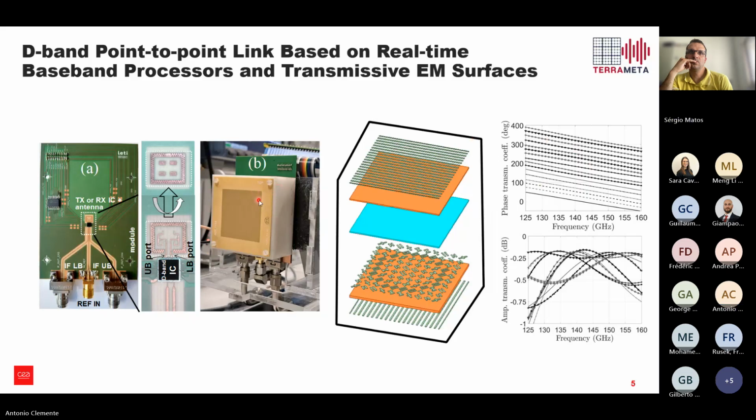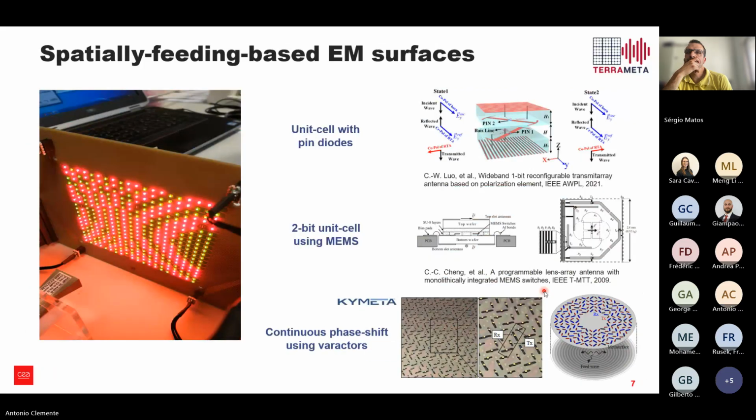When we increase the size of the antenna, due to the fact that this is not a true time delay device, the bandwidth varies, but it is more than 10% in any case, and you can achieve between 10% and up to 30% as well, as you can see here, with very low losses. So this is the case of the passive design.